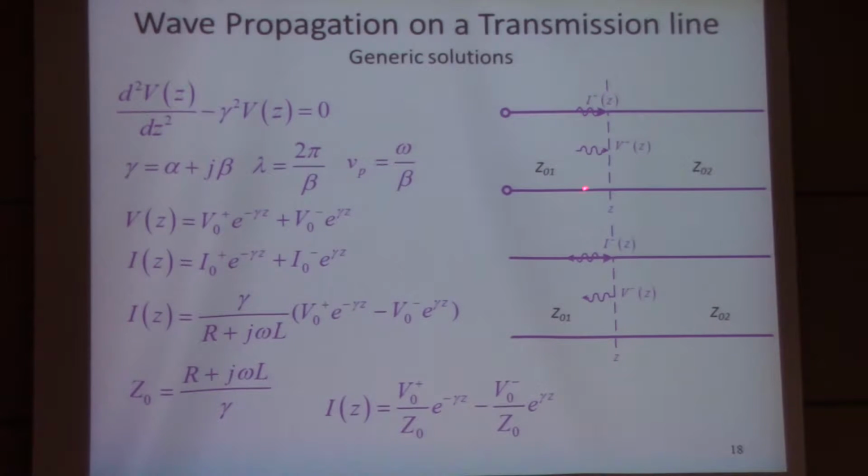If these two characteristic impedances are different, you will get a reflection at this interface. So that's kind of different from DC, right? The reflection, and you will have, of course, transmission. Two parts. But if these two characteristic impedance values are matched, you don't have reflections.